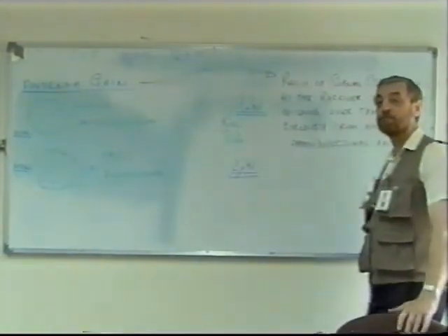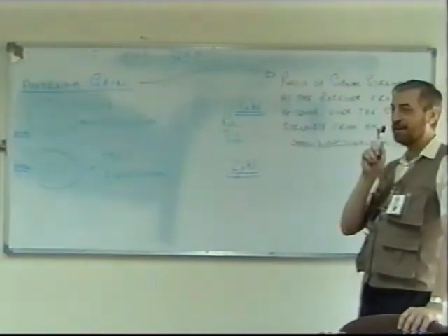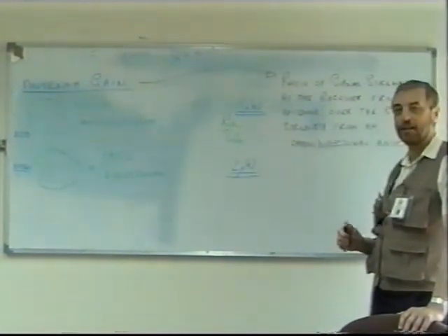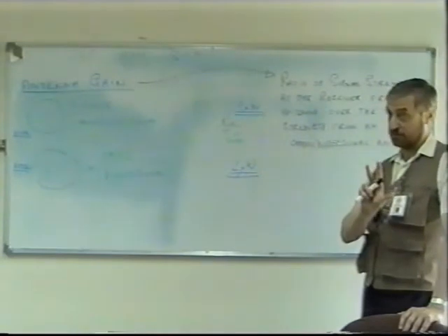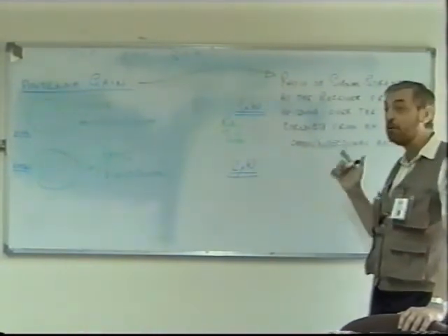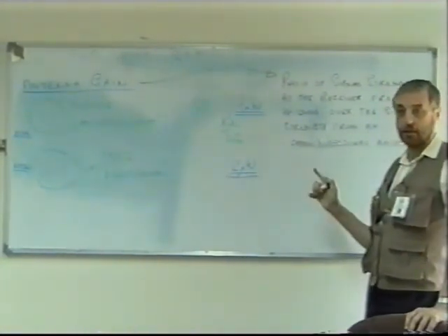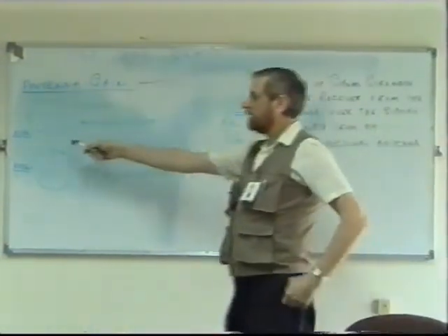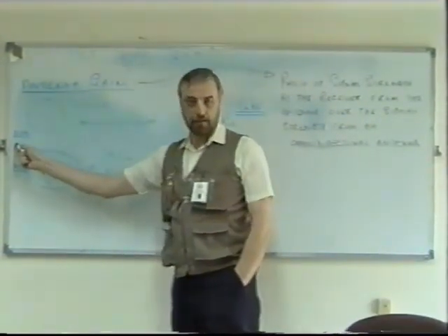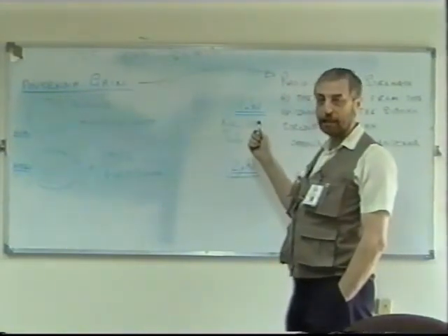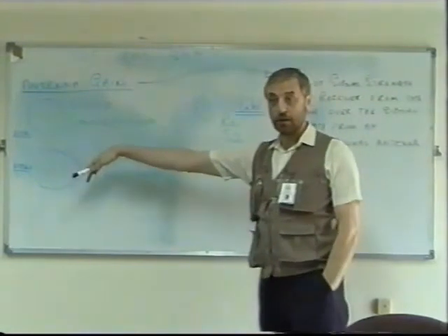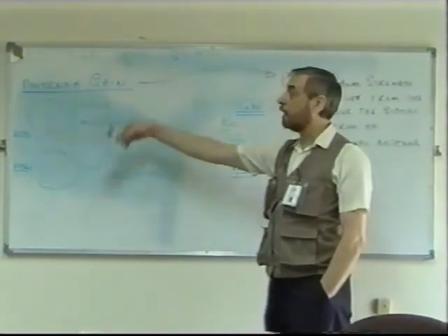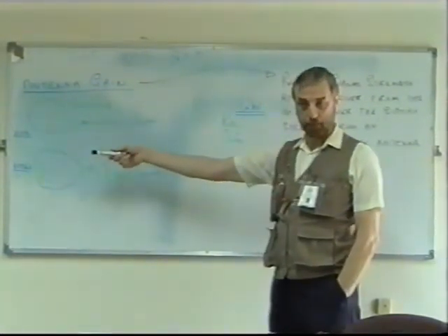The dBm is comparing to 1 milliwatt. That's if you're measuring power itself. Just power, yes. But here we're measuring just the power ratio. In other words, I might not have 100 watts here. I might have much less than 100 watts. I'm going to get much less power here. I'm not actually measuring power. I'm measuring what it is compared to what I would get from an omnidirectional antenna.